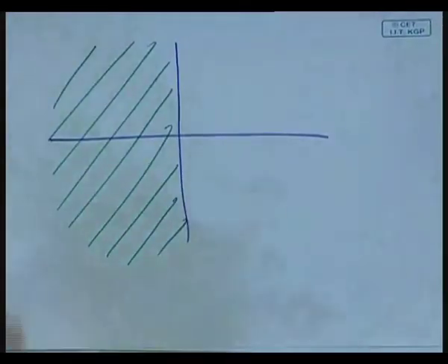Can't we call it sustained oscillations? Yes, if it is exactly on this, it will be sustained oscillation, exactly complex conjugate imaginary eigenvalues. So, it will be exactly sinusoidal oscillation, undecaying oscillation. That we can call stable in a different sense. It is called marginally stable, in a different sense. Yes.